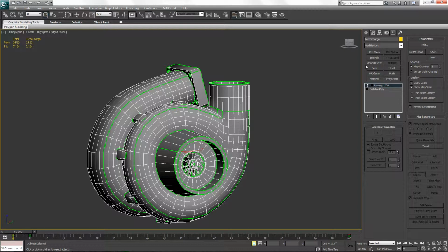But you should know that you can't take full advantage of the texture map types unless you've already unwrapped your geometry objects. Also, 3D Studio Max allows up to about 99 different UV sets. When exporting to Replicate, only UV channel 1 will be brought over. So on to the map types.